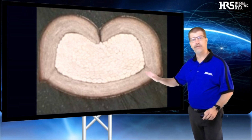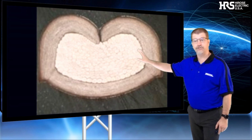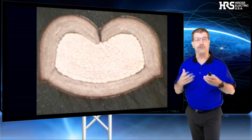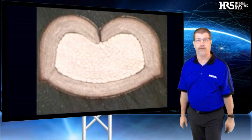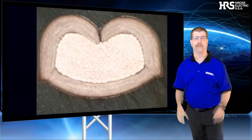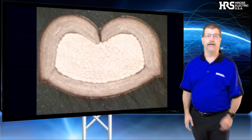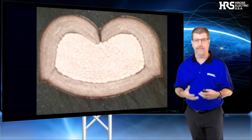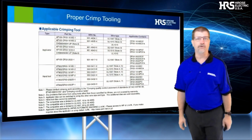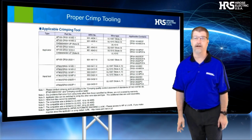What you can note here is the even shape of the contact body, and you can also see that the conductor strands are all compressed together properly. Air gaps are minimized, and the material is evenly dispersed within the crimp. The crimp tool plays a critical role in the making of this contact and getting it right, making all of this happen. Hirose offers a line of both hand tools and applicators for usage with our contacts.